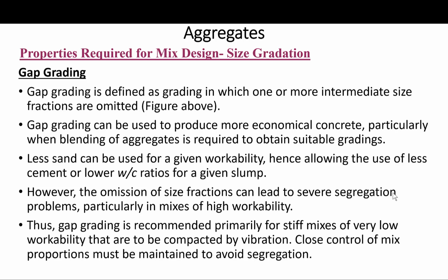Other specifications may require much narrower limits, depending on whether rounded gravel and sands or granular crushed rock and manufactured sands are available. The amount of fine aggregate passing the 300 micrometer, number 50 sieve, and the 150 micrometer, number 100 sieve, affects workability, finishability, bleeding, and so on.